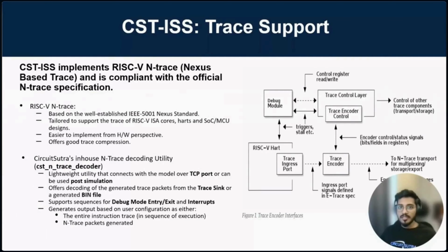In addition to this, CST has developed their own decoding utility that connects with the model over a TCP port. It supports packet generation for debug mode entry, exit, and interrupts, supports configurable output generation, either instruction trace or the decoded messages, and also parses the trace data from a bin file, which is configurable.